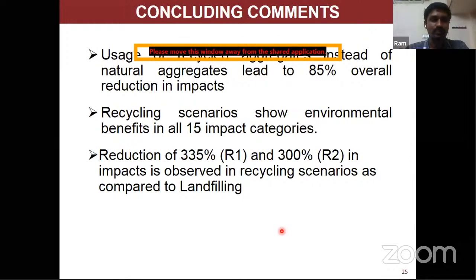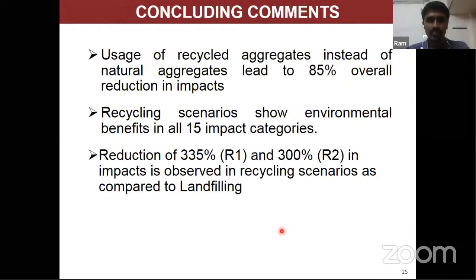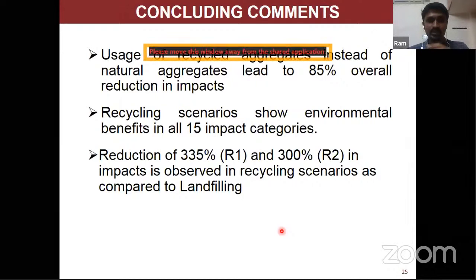So to answer the first question, the cost actually depends entirely on the transportation distance as well as the capex. To give an indication of the capex costs involved, the capex alone can be about 150 rupees, that is about $2 per ton. And the operation cost can again be another 150 rupees per ton, that is again about $2 per ton. But I am not including the secondary collection or the primary collection in this figure. So about $4 per ton itself will go into capex and opex, and your collection and the land involved are not included in it.